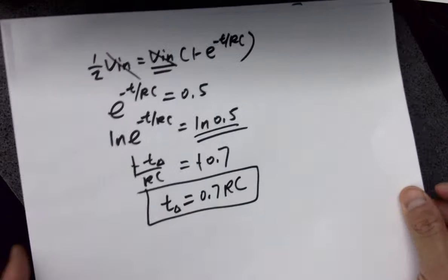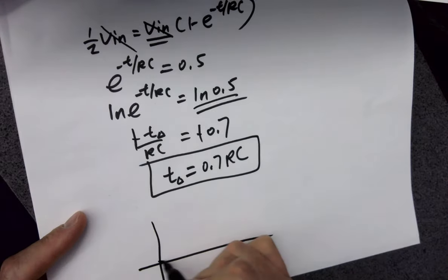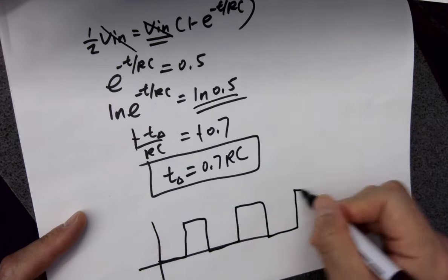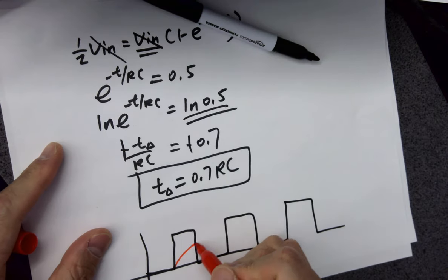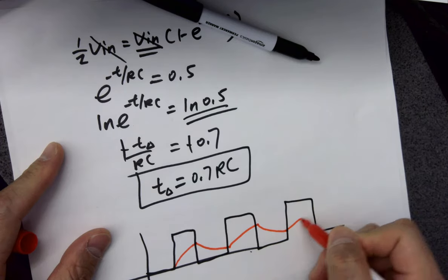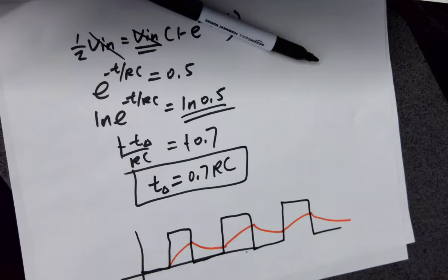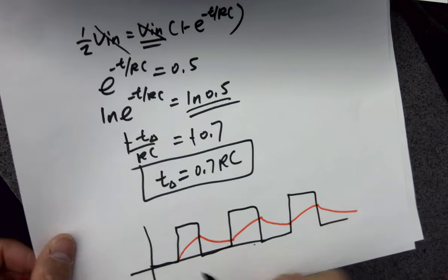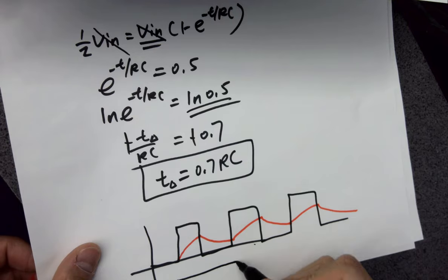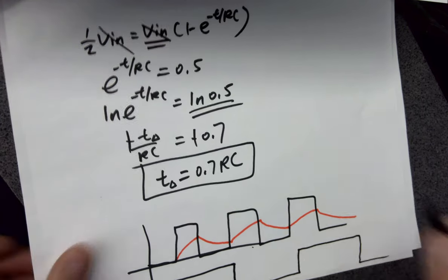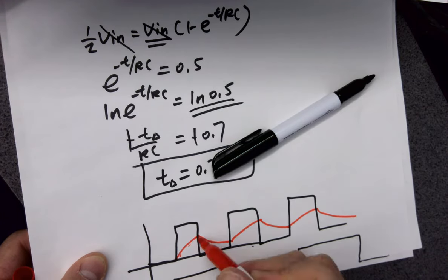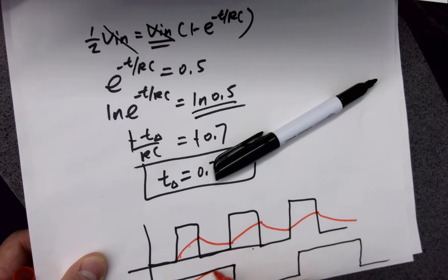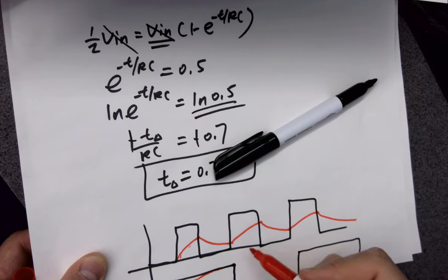So what is the case of a failing digital circuit? The clock, you are trying to drive the circuit. You have a digital input, you are expecting a digital output, but eventually you are getting something like this. What's happening? Anyone can tell me what's happening? Do you have enough time to charge it up? For example, I give more time. Give more time. What's gonna happen? Same. Okay, it reaches here. Since I have more time, it has time to charge up. Okay, then it works.